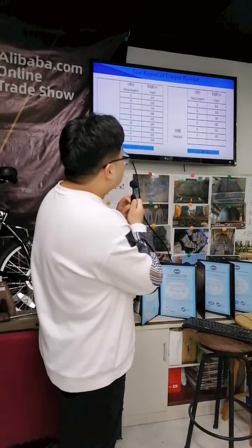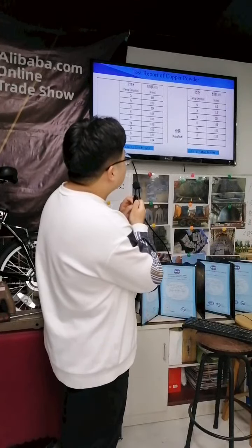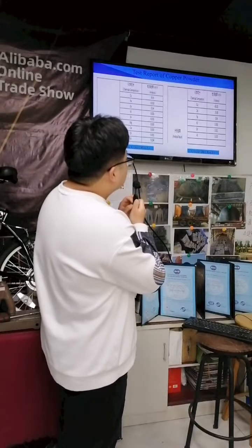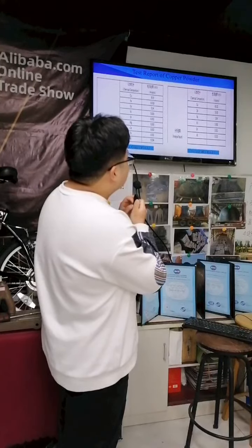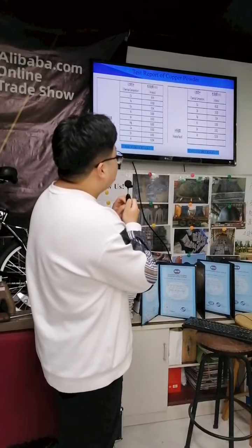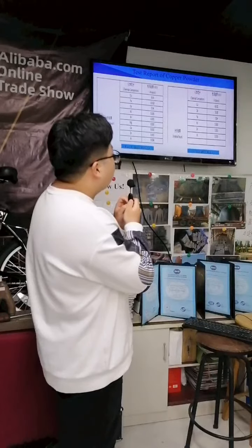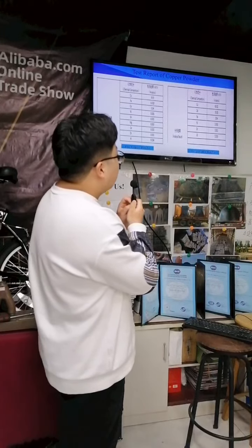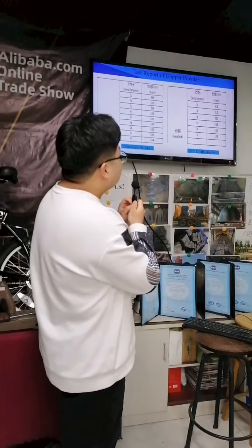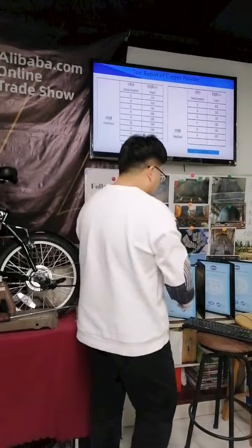The second chart is the analyzed result of copper alloy powder. Copper alloy powder contains 60.2% copper, and the zinc is 39.83%. The iron is less than 0.04. The nickel is less than 0.005. The tin is less than 0.01%. The aluminum is less than 0.002%.